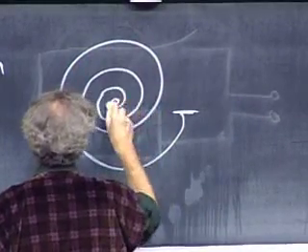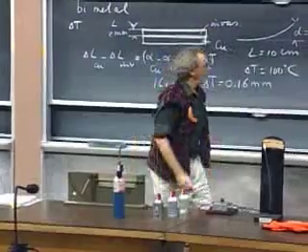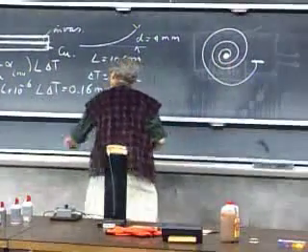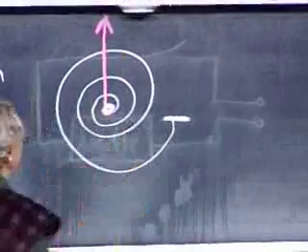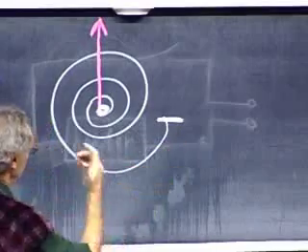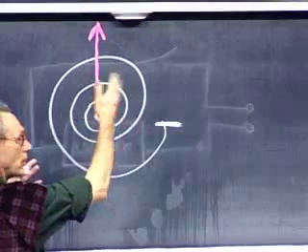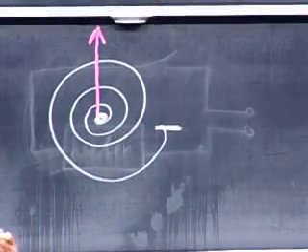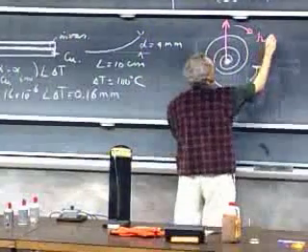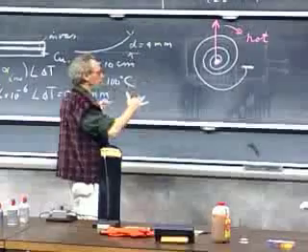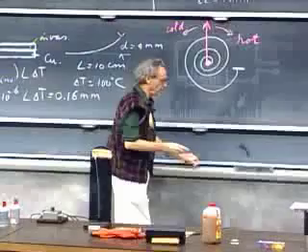There's a coil. This end of the coil is attached to the plastic casing. And here is the red hand. It's a pivot here. So this is fixed. This cannot move. I heat it up. What will happen when I heat up? This is already a bimetal. It's already curved. But when I heat it up, it will tighten even more. It will curl up even more. And when this one curls up even more, it will go into this direction. So this is when the temperature increases. And when it, of course, gets colder, it will uncurl, and so here is cold. And that's what the whole thermometer is based upon.